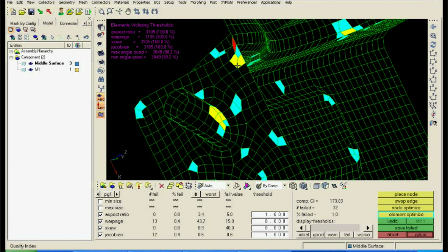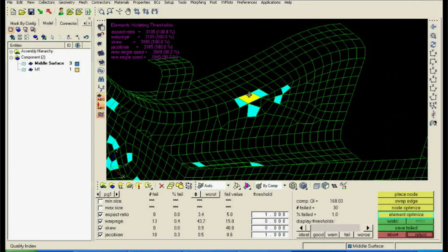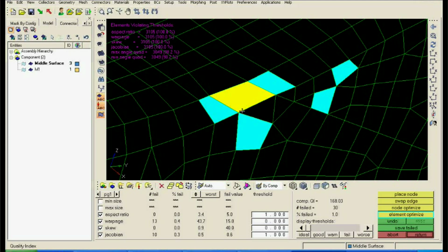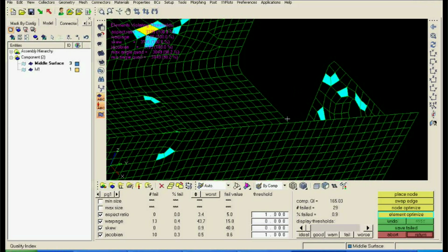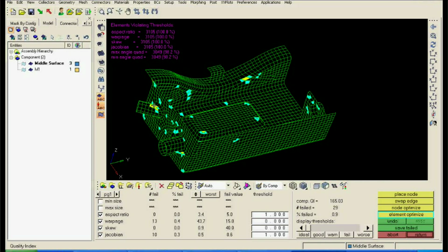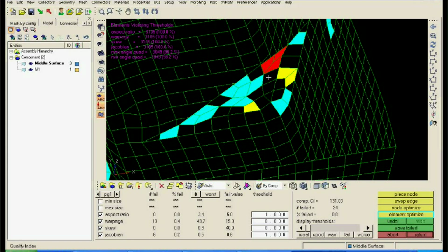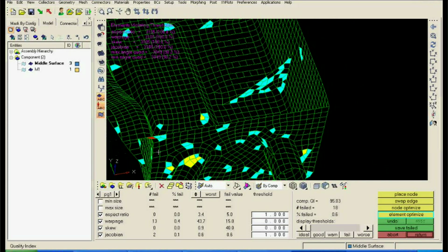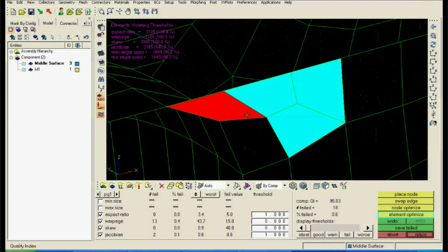This is quite a big element. This is a very big element here. So it has come down to 160 from somewhere 14 or 15 hundred when we started. And again, such triangular shapes will also always have some issue for sure. Okay, 95. This is quite tricky. This one here will be difficult to manage because it's such a complex shape. You can see there are two surfaces which are meeting up, and the edge is just passing through them.